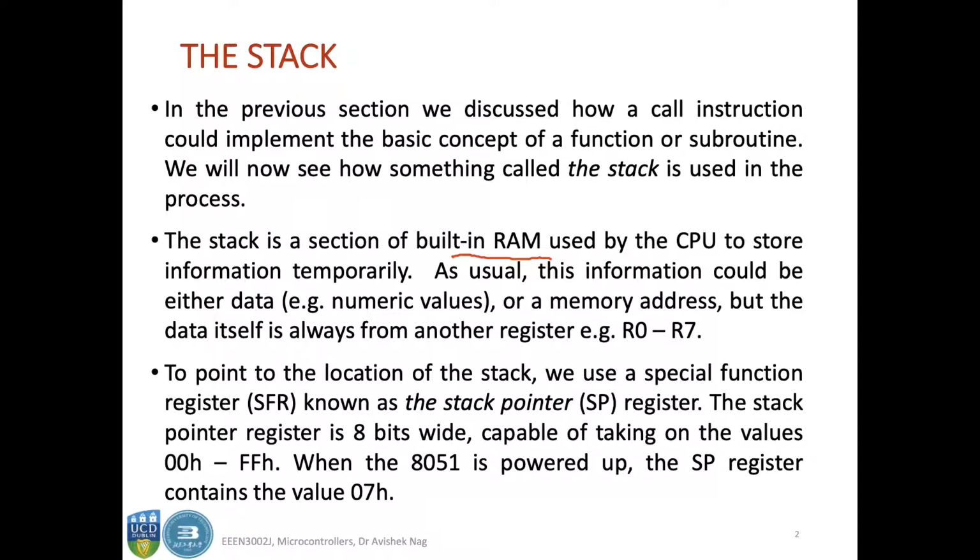Another register called the stack pointer is also there, which is associated with the stack. So this stack pointer register points to the location of the stack. The stack pointer register is 8 bits wide, and it is capable of taking values from 00 to FF.